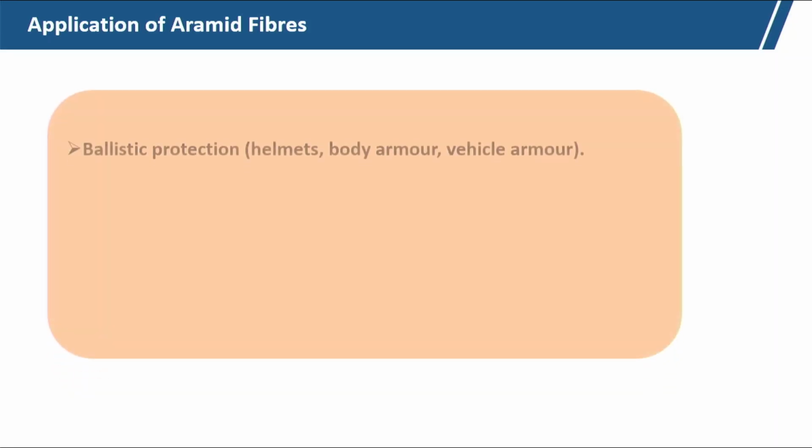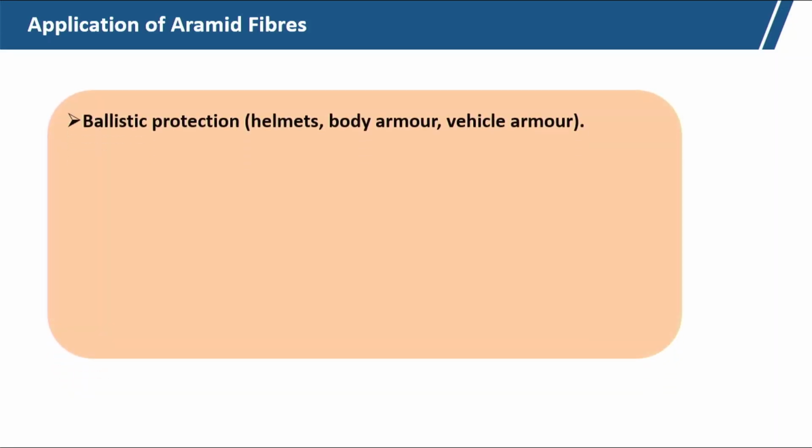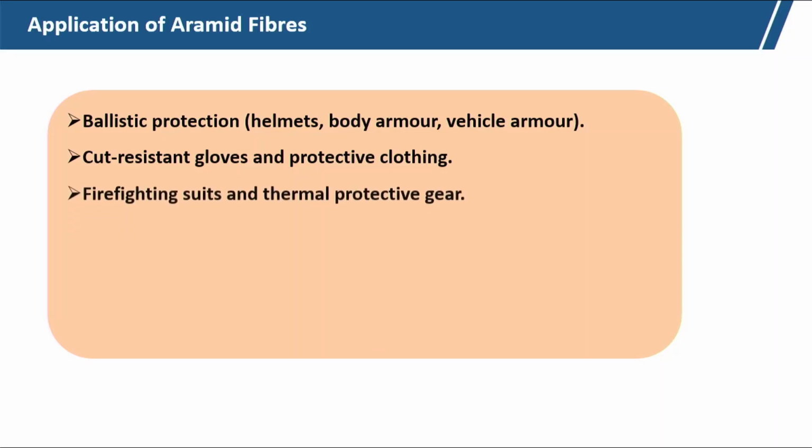If you see the applications of aramid fiber: ballistic protection, helmets, body armor, vehicle armor. So, where impact strength is important, there aramid fibers are used. Cut resistant gloves, protective clothing. For meta-aramid we can use it for firefighter suits, thermal protective gear, okay. And for ballistic protection, we can use para-aramid.